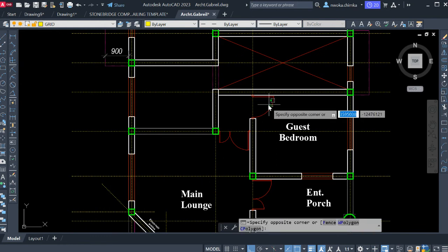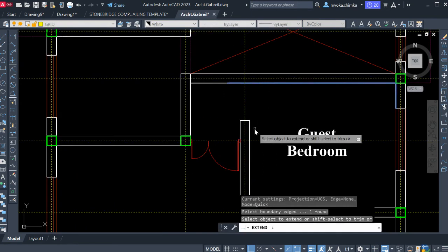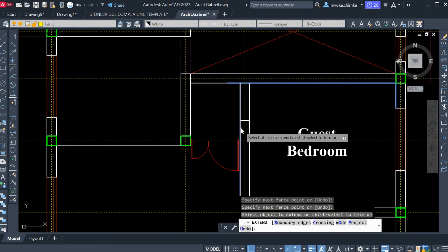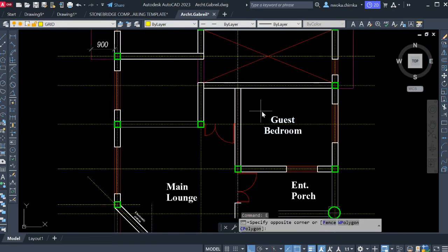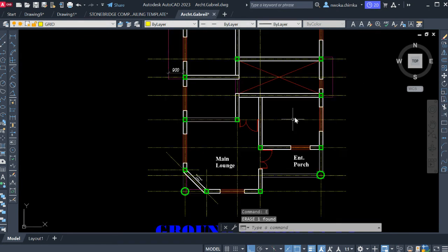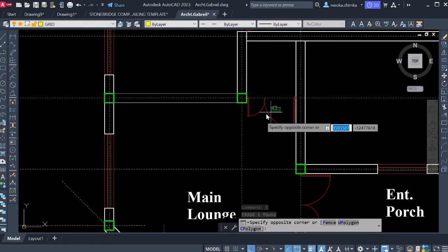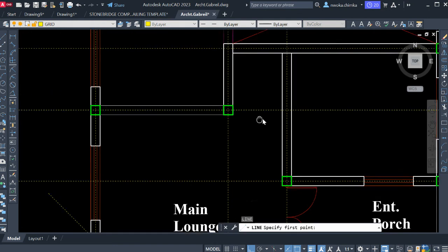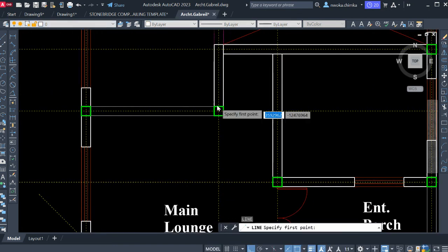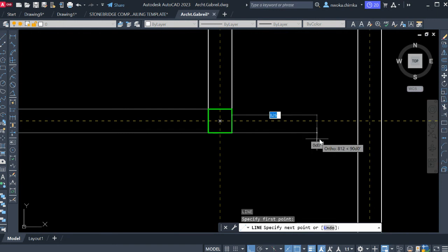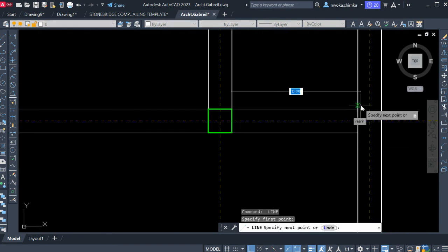So I'll just remove this wall right now and then extend this beam or this wall to use this place as my beam, and then this is now one panel. So I'll just remove this right now and remove them. And also the same thing happens here right now. I will remove this door, and then I'll just create, let me use color 0, a beam which does not have any wall load on top of it. So I'll just leave it.